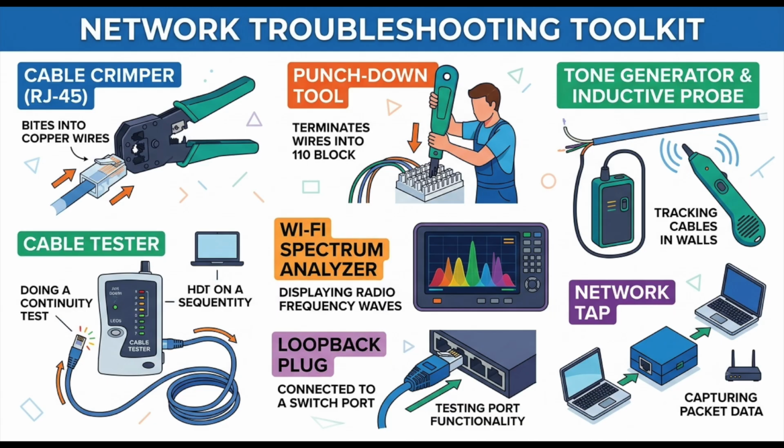As the probe gets closer to the electromagnetic field created by the tone generator, a speaker on the probe starts converting that invisible field back into sound. The closer you get, the louder the screech. So the probe literally screams when it finds the matching wire. Yeah. Marco has found Polo. Yep, you've isolated your cable.